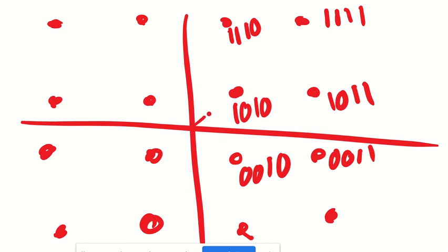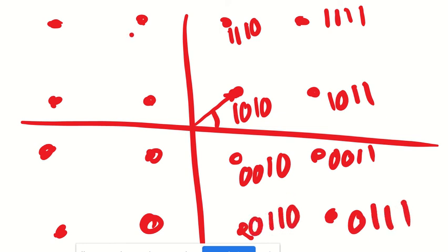You see, each of them has a different magnitude, amplitude, and phase. So depending on where it is on the constellation diagram, it gives you an idea how each 4 bits is getting demodulated. So you know in advance, if you get a signal with this amplitude and this phase, that will be 1101.